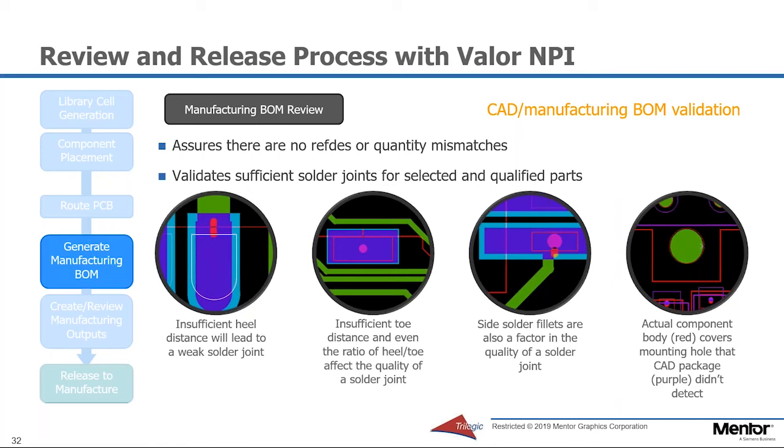The component outline data can identify other issues. For example, shown here is a case where the actual component body, shown in red, covers a mounting hole that the CAD package outline, shown in purple, didn't detect.